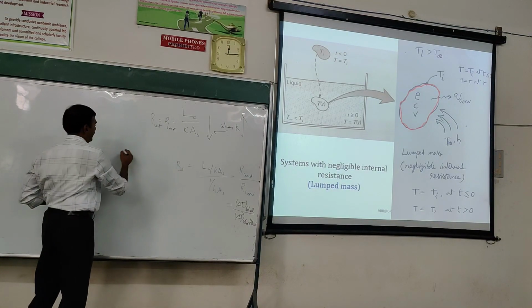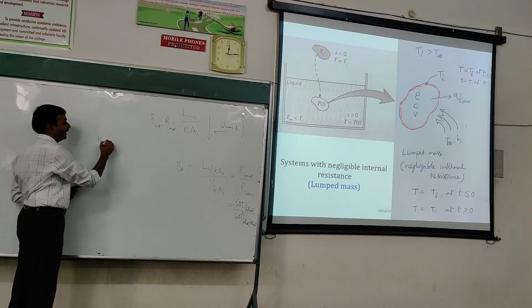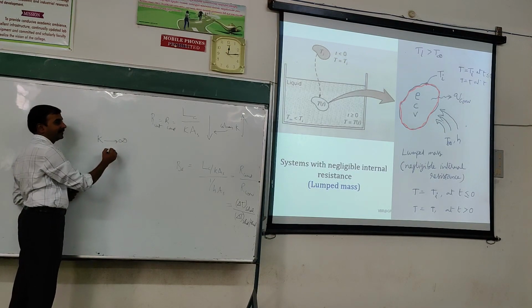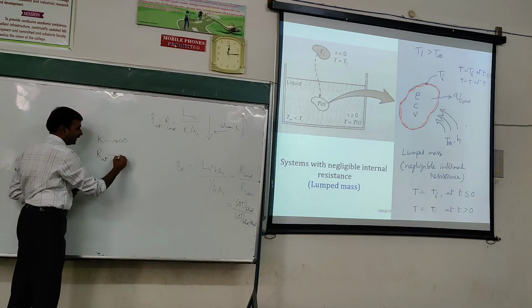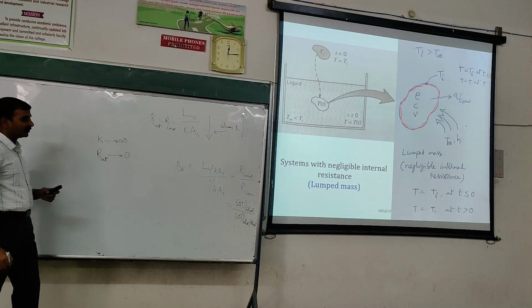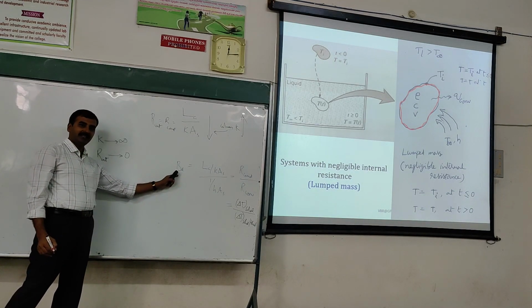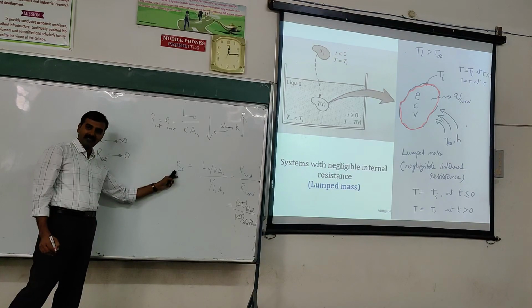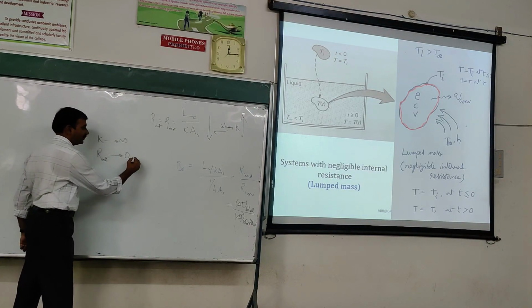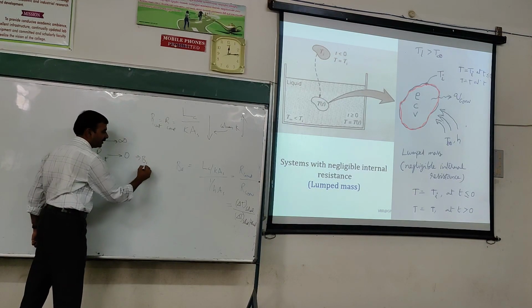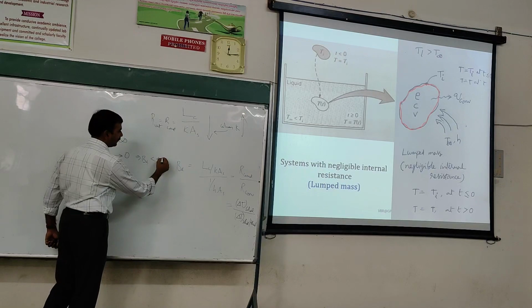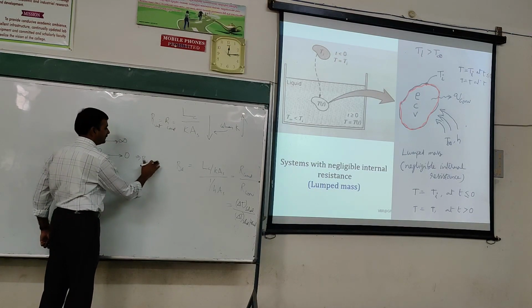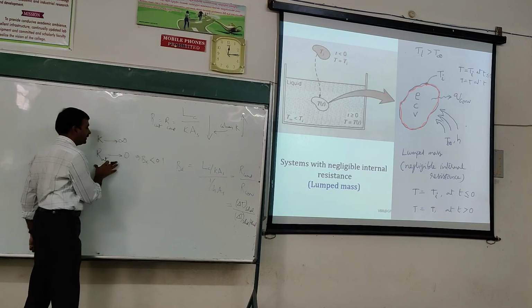So, for larger values of K, as K tends to infinity, this internal or conductive resistance tends to be 0. So, suppose if internal resistance is closer to 0, if not 0, then what will be the Biot number value? Meaning of this is what? Biot number will it be less or more? Is very, very less, in fact. So if it is less than, say, up to 0.1, if you want to put it, if it is less than 0.1, this approximation is good.